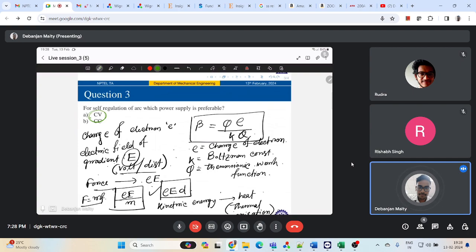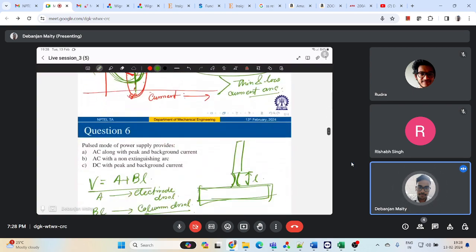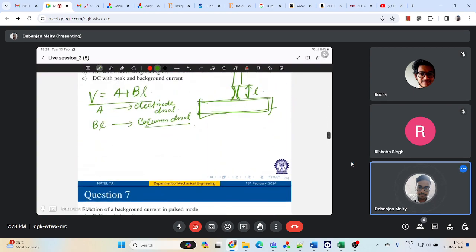There I missed one thing, there was one point where you had those combined characteristics of power source. You talked about this EGW, right? Electrogas welding, where we basically provide both constant current and constant voltage characteristics, right? The high voltage portion is the constant current characteristic, and so it will look something like this. Let me draw over here.